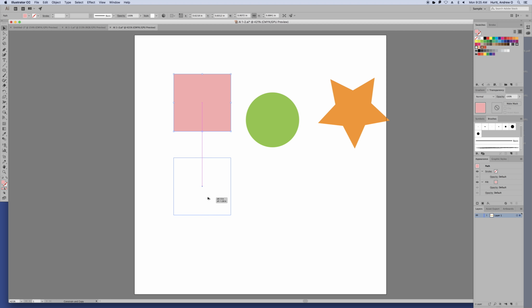So if you hold Shift, like with almost any other program, as I'm holding Option and Shift, I'm copying. But when I'm holding Shift, see how I'm kind of floating a little bit with my mouse. Holding Shift sort of forces it to align, so you're not moving it off center. If I'm not holding Shift, it's easy for me to move it off center. With the smart guides, you can keep it aligned a little easier, but holding Shift sort of forces it. There you go, it doesn't really move out of alignment until you really, really force it.